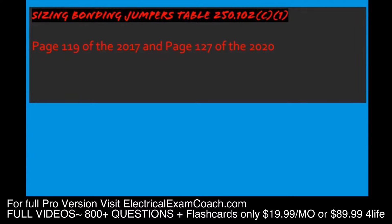Now we're going to learn about sizing bonding jumpers. This is done in Table 250.102(C)(1). Now there's not a tab for this one, but if you watch my how-to-make-your-own-tabs video that is back in week 1, it will show you how to make your own tabs. And this is one of the ones that I highly recommend making. I call it bonding jumpers or something like that.